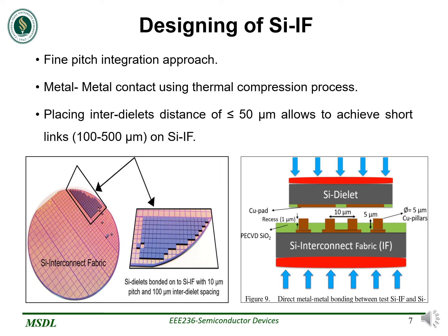Our substrate is rigid silicon with a silicon dioxide dielectric layer, which acts as the interconnection platform for the entire system. The wiring in the dielectric layer is compatible with the mature back-end of the line technology in CMOS fabrication. The feature size of wires in back-end of the line technology can be as fine as 0.5 micrometer, which is a 20 times reduction from feature size on organic boards.